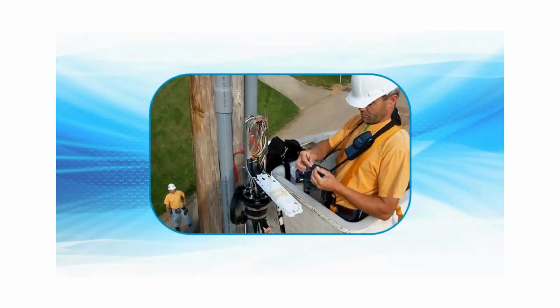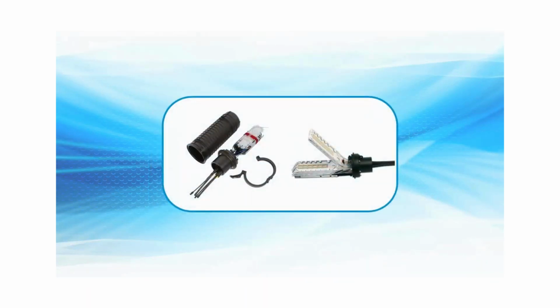The drop cables from each customer premise are then connected to the outputs of these splitters to complete the network connections. The cascaded with closures architecture is typically spliced from the hub closure to the splitter inputs at the fiber access terminals. The feeder fibers are spliced to the splitter inputs, and the distribution fibers are spliced to the splitter outputs. In the fiber access terminals, the distribution fibers are spliced into the splitter inputs. There are pre-connected adapters on the splitter outputs to allow fast connections with pre-connectorized drop cables. This half-spliced, half-connectorized installation accounts for the majority of today's cascaded networks.